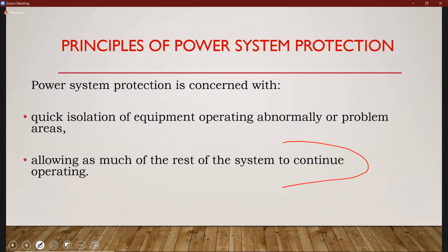So you have 14 circuits coming inside there, to, of course, use for your supply. If you have a fault in the living room, and it's a fault associated with the plugs, you would just want the breaker that deals with the plugs for the living room to trip. And when it trips, only the living room will be out of service.